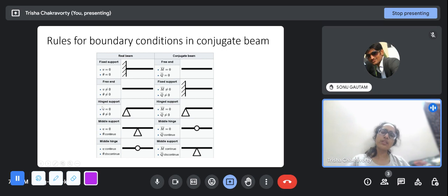A hinge or a roller support basically is equivalent in a beam, because in a beam we don't allow axial displacement. So transverse deflection is restrained and rotation is freely allowed. And similarly, in a hinge support, moment is zero. Since rotation is freely allowed, there can be any theta. The moment at a hinge support is zero, which we again saw during the bending moment diagram.